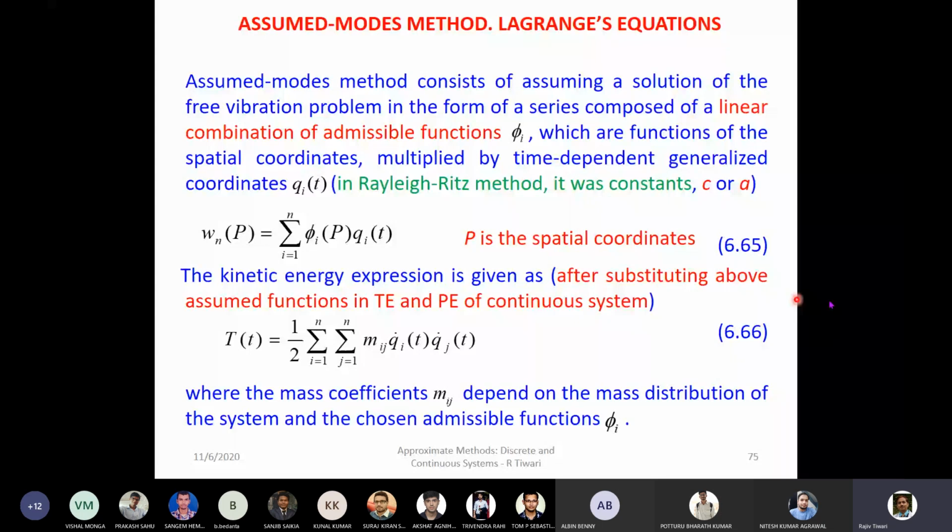With the Rayleigh-Ritz method, the main difficulty is that we need to choose the comparison function. We discussed something about the Rayleigh-Ritz method, the re-examination of the boundary conditions. And in that case, we could choose admissible functions instead of comparison functions, which have less requirement.